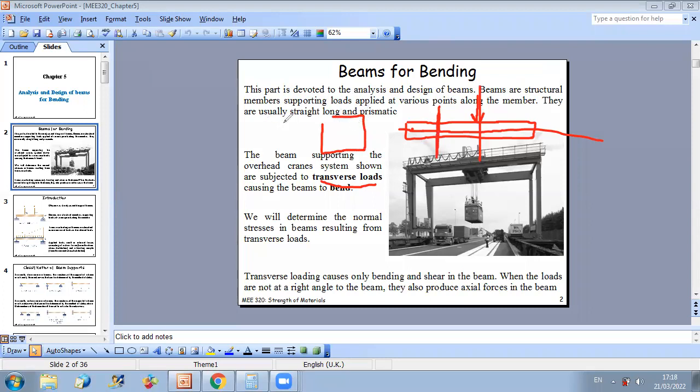So let's say you have for each elementary area a shear force applied, and the total shear V will be calculated as the integral of shear stress times dA. So overall, because of the shear stress distribution within a cross section, if you add all elementary forces, you will get the total shear in a cross section.